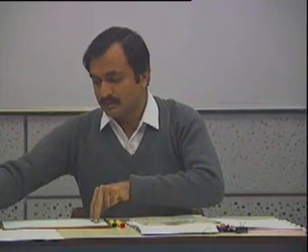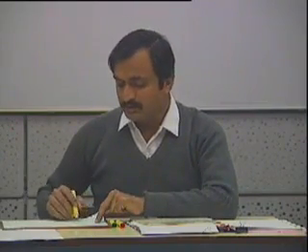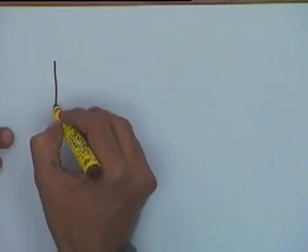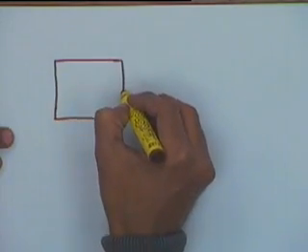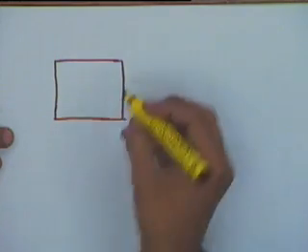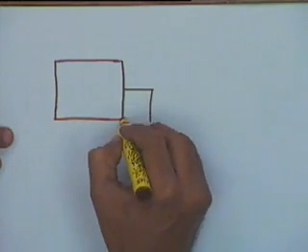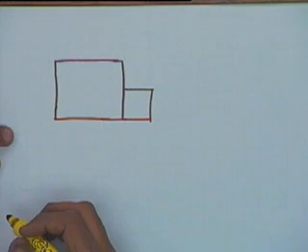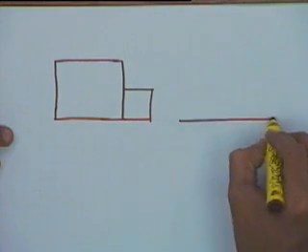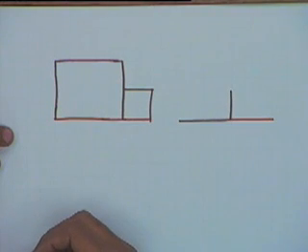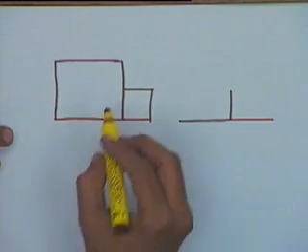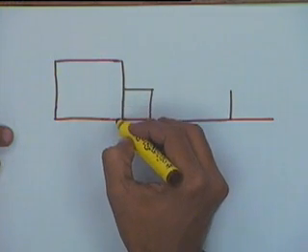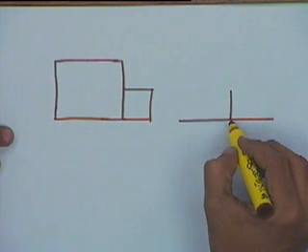But one thing that we have to be careful about in using these operations is, let us take a simple case, if we have a two dimensional square, and we take another two dimensional square which is like this, and we try to find out the intersection. The intersection of these two, strictly speaking, would be a straight line, because the set of points which are common are just these points. So intersection of these two will just be a straight line over here.